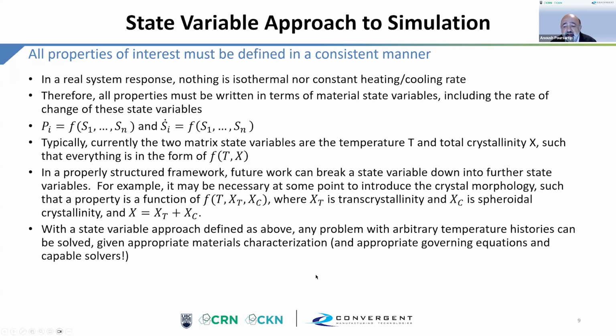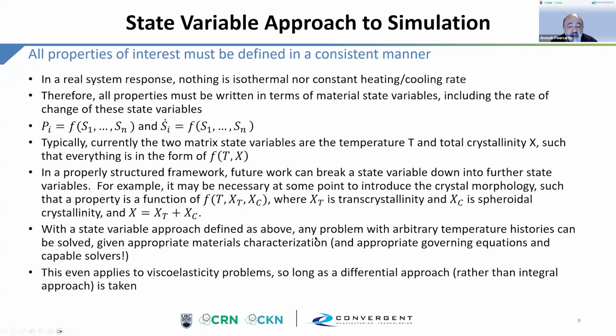Again, if you do this right, you can cope with any arbitrary temperature history, and I'm going to show you an example of that, actually a couple of examples of that in my case studies. As a side note, this applies even to viscoelasticity, as long as, again, you use a differential approach, which then makes it consistent with the rest of the framework.